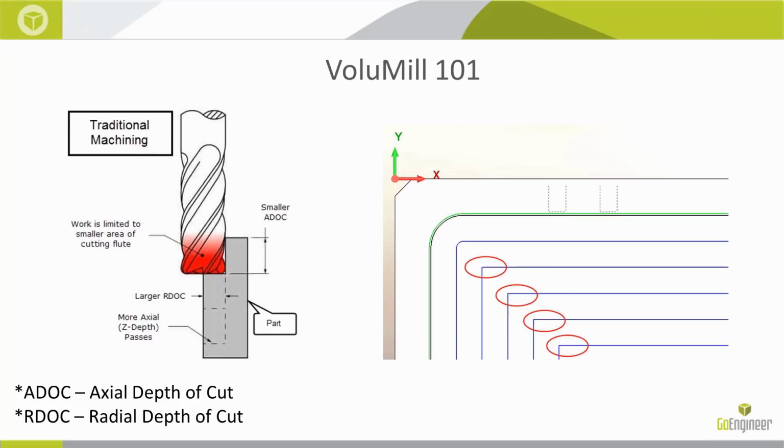into the other direction. For those of you who are familiar with any kind of pocketing machining, everything will sound fine, and then all of a sudden it gets into that one corner, and you're going to hear a chirping sound, or as I like to affectionately call it, the machine is barking at you. That's where you have the loading and unloading of the tool and the cutter inside of the material.